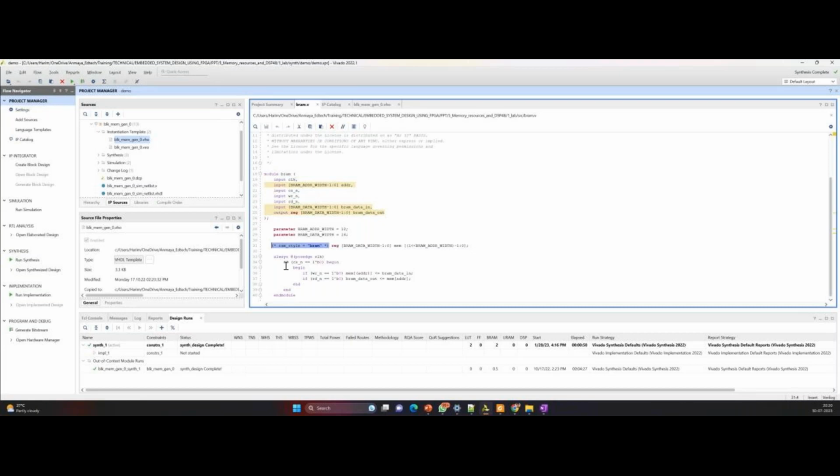There are some debug pins, right? For example, assume you want to test the SPI protocol. What you do, for SPI MOSI and MISO, you instantiate both the slave and master inside the same FPGA, and through an external connection, loop it back. I mean, the slave and master lines you just connect by shorting them with a wire. So what will happen? You can actually test it through Signal Tap, everything you can test.